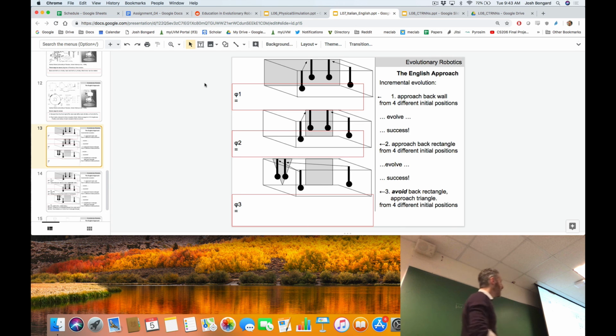The first behavior is they're going to place a black piece of Bristol board on the back vertical surface of the table behind it, no obstacles on the ground, and they're going to reset the gantry robot to these 2 initial positions. Start at this initial position, the robot moves. When it finishes moving, they command the gantry robot to move to this position, then release it, and the neural network controls the gantry for a second time. So each neural network has 2 attempts to move. In this case, the fitness function is very simple, which is approach the back black wall underneath the table.